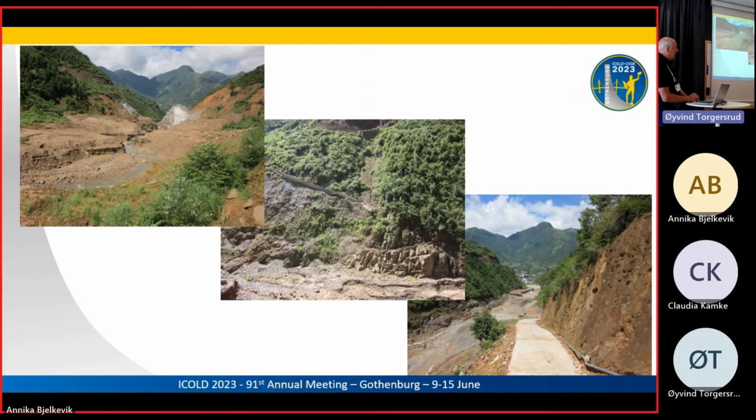And this is an example of a dam that didn't work. This is in China. I went to China to do an inspection of this dam, but found out that it failed the year before. In this case, they had a pretty good spillway system. It wasn't a surface spillway. It was a tunnel, like a glory hole type of thing, with very large decant structures upstream and a tunnel that went through the foundations of the dam to the downstream.